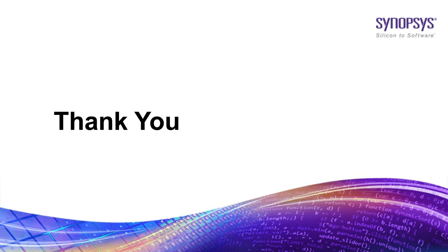Now, repair uses the concept of redundancy, that is, having extra bits in the memory that are sitting there waiting for utilization. It's like the extra tire you have in the back of your car. You have extra bits in the memory, and those bits can be reconfigured such that they would replace some defective bits in the memory. Now, having extra spares and having defective bits are possible, but with those, you need the intelligence.